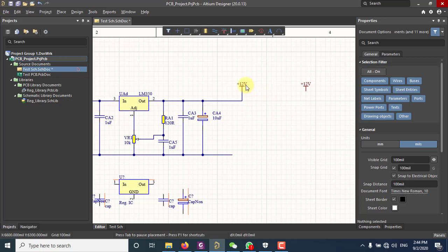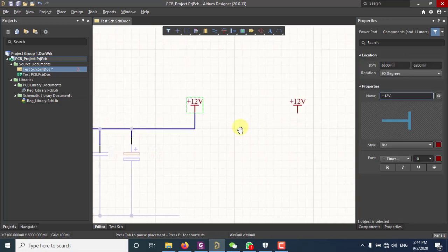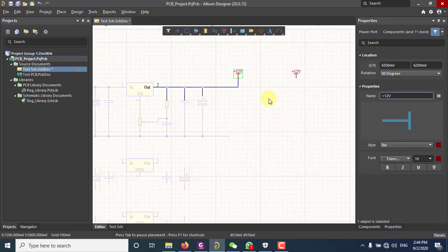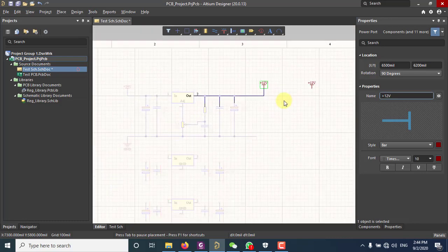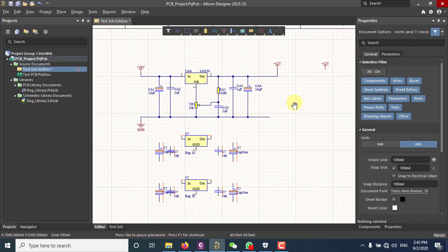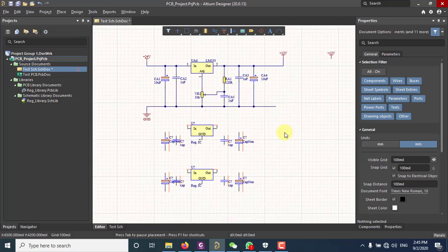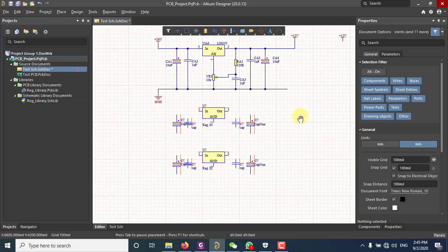Again, press the Alt key on your keyboard and then click on that net, and you can see that the only part in the circuit where this net is used is here, and it's also connected here. In addition to using Shift C, you can click somewhere in the schematic workspace, and your selection is cleared.